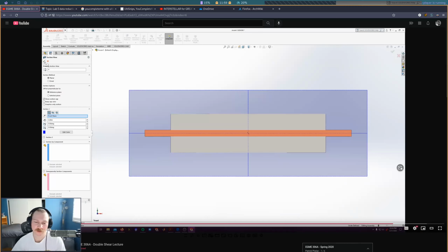So this bearing stress that we have on this rod is over their shared area with those 3 metal discs, starting from this edge, going all the way over to this edge here. But in the end, we're just going to calculate the bearing stress for this center portion here. You can't see the cuts right now for the 3 different discs, but basically we're calculating the bearing stress for the length of the rod, around here. And that's going to be equal to that length of the rod here multiplied by the diameter of the rod. Right?